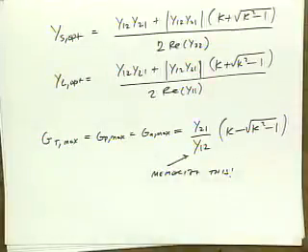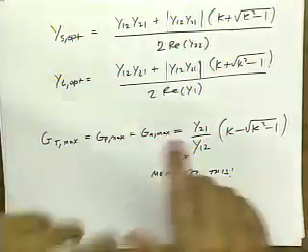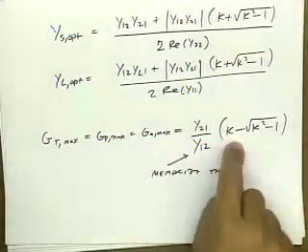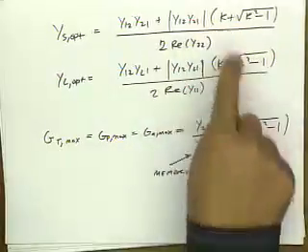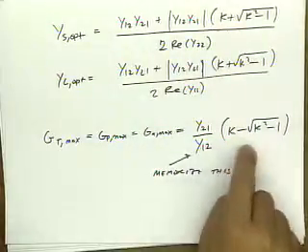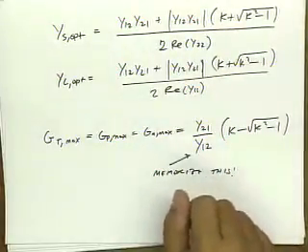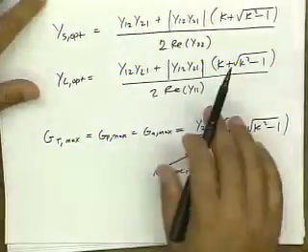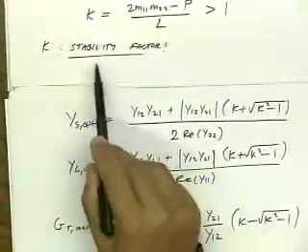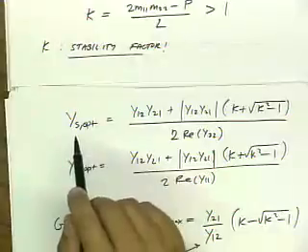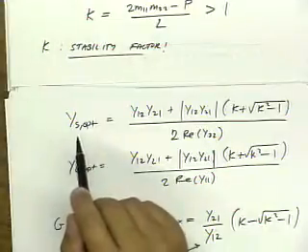So we haven't done anything magic. All we've done is lots of algebra, and this problem is so important that after doing all this algebra you decide I should clean things up. And when you clean up the results, you say, oh, the results look nice and clean if I define this k factor. And notice here it's plus, here it's minus. This k factor plays a very important role. And of course its name is a giveaway, dead giveaway. It's related to stability, unconditional stability of the two-port.